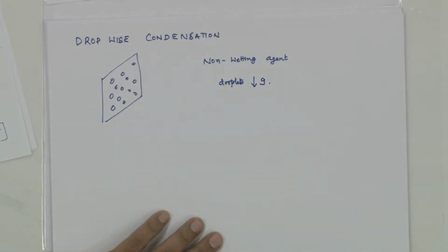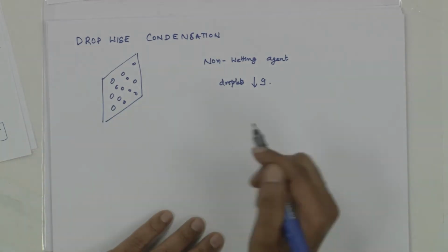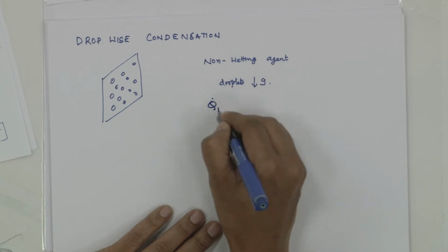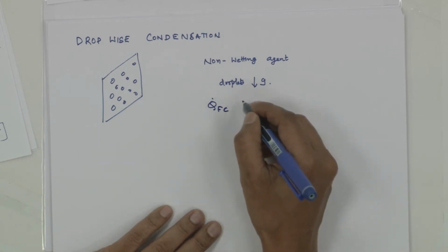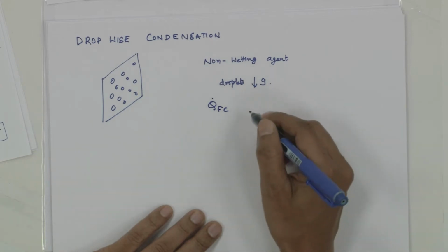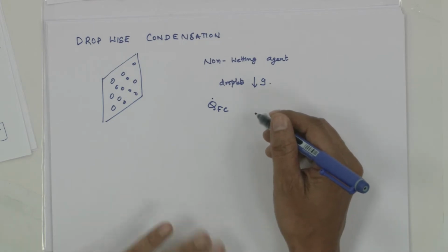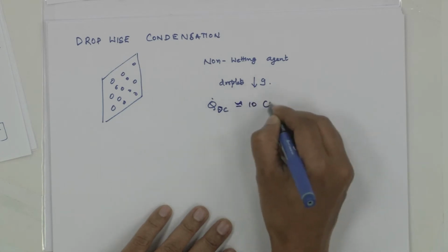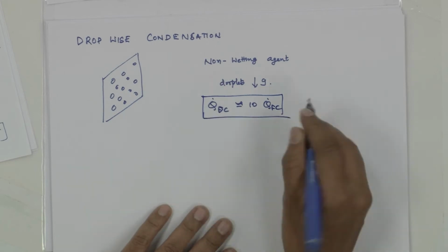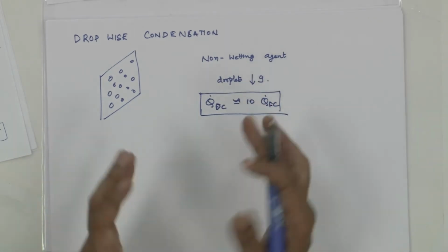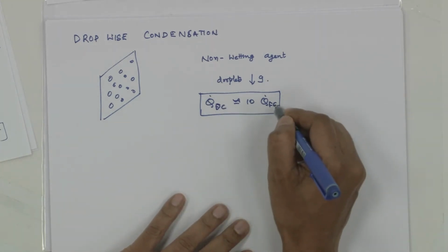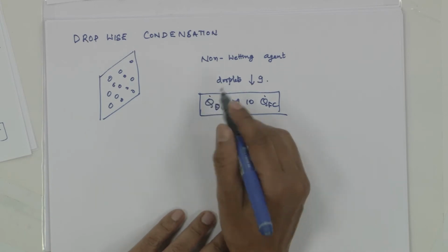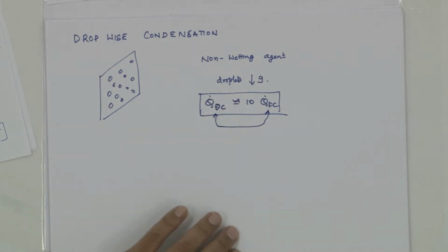So this is what is called droplet condensation, and naturally the droplet condensation would create less resistance because it is not a whole blanket. Generally, heat transfer rates more than 10 times are associated with dropwise condensation, approximately 10 times the film condensation. It's too coarse to make this statement, but still, just to get the feel, the film condensation is not good compared to the dropwise condensation, because the heat transfer rates in dropwise condensation are very large.